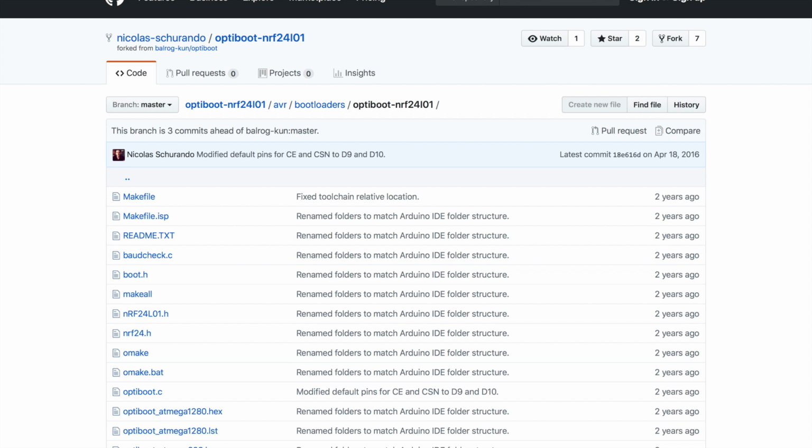And when you're connected via USB to the computer and you want to flash something from the Arduino IDE, what happens is that the USB resets the board, and then it gets into the bootloader, and the bootloader waits for a couple of fractions of a second to see if someone is talking to it with a known protocol over the USB, over the serial actually, and it's gonna take the bytes that are coming from the serial and override the sketch that used to be there with the new sketch coming through the USB, through the serial.